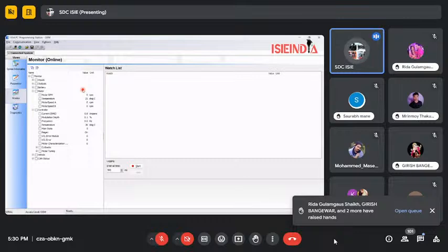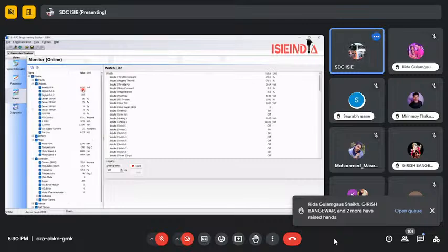This is when you connect the Curtis controller with the driver to your PC or your setup. You can see that I have connected and taken some screenshots to show particular variations, the predefined functions, which function I'm using and which I'm not using. What were the pulse modulation signals when we had the initial throttle, and what were the losses?